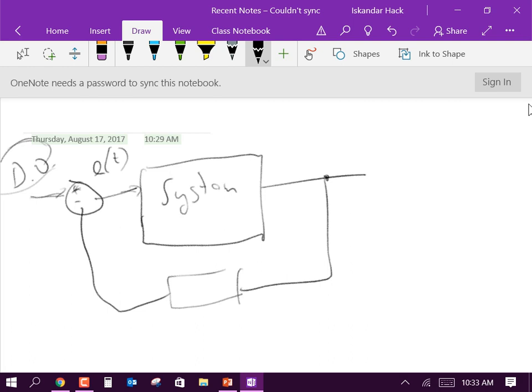And typically the way that works is that it's measuring the speed coming from a sensor on the transmission, usually, but it can be elsewhere in the car. And it goes through some processing. So whatever speed is on the car at that time goes into my feedback as my desired speed. And it's a capacitor that just holds a charge with an op amp so it doesn't bleed down.